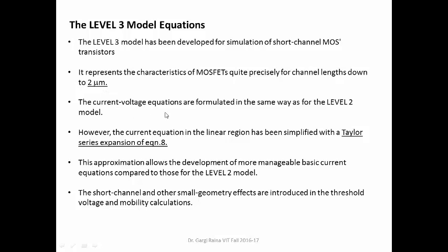The current-voltage formulation is the same as for the level 2 model. However, the current equation in the linear region is simplified with a Taylor series expansion of the main equation that we discussed in level 2. This approximation allows for the development of a more manageable basic current equation compared to that of level 2.